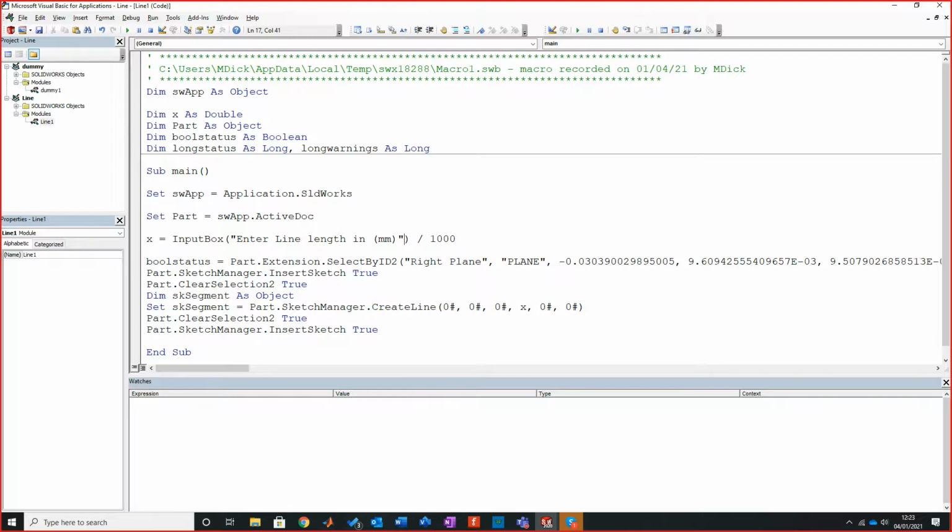So on here, I'm going to go comma. I'm going to give it a title of X length. There is a reason I'm doing that. And let's stick a default in there. I'll give it 10 millimeters. Oh, 10 millimeters. So, what did I miss? Oh, tell you what I did. Forgot to put it into quotation. Because when it's in a quotation, it will take that as a label and bang it on where it's been assigned to.